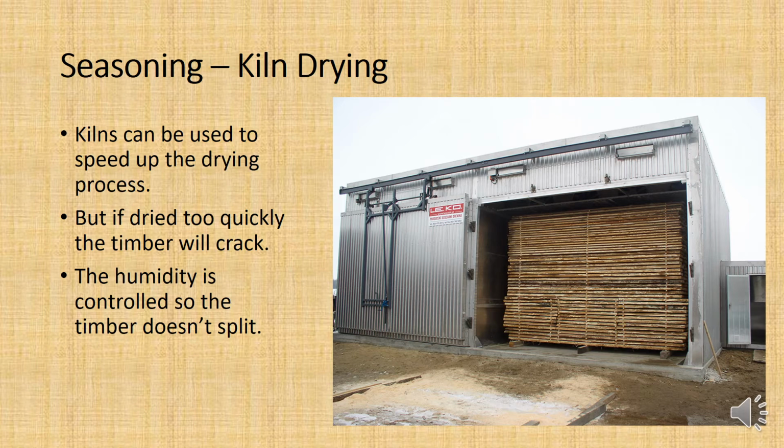But the other thing is, even if you don't reach the point of combustion and it doesn't catch fire, if you dry it too quickly, basically the timber will crack. That means as water is sucked out of the timber between those cell walls, those wood fibers inside the wood, those cell walls will not stick to one another with the lignin, that natural resin that they emit.